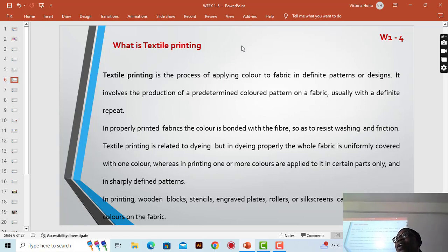So we have geotextiles, where there's something like a net, a wide net, but heavier, not just like the mesh we used to sew. When roads are being constructed, when they grade the road and they are ready to put quarry on it, they use it to lay the foundation of the road. So they lay it like a carpet, like that. It is to prevent erosion and to prevent the spoiling of the road at an early stage.